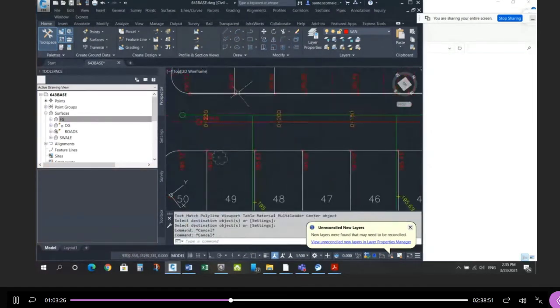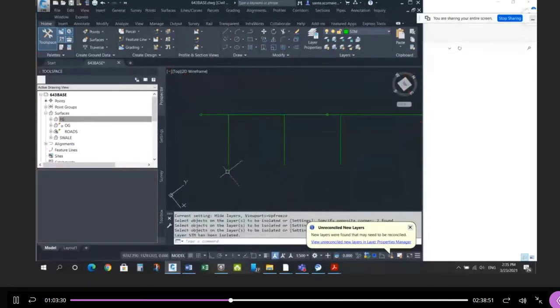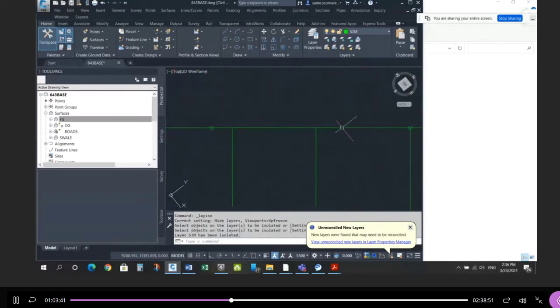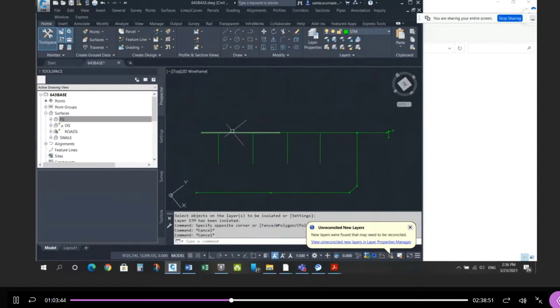So if I look at my storm sewer now, it includes these leads, right? Backyard, backyard, backyard. Oh, and I missed one. Match properties. And look at it again, and there's my 4 backyards, right? These 2 catch basins connect to this street sewer, and these 2 catch basins connect to this street sewer.